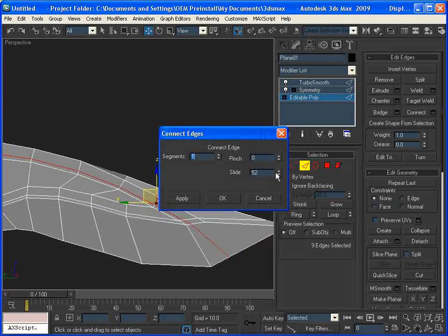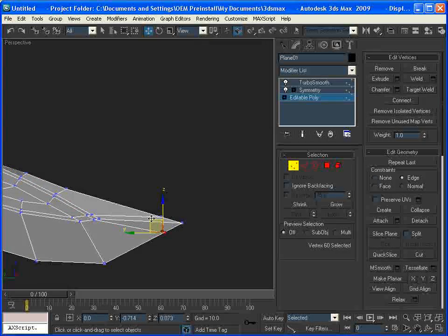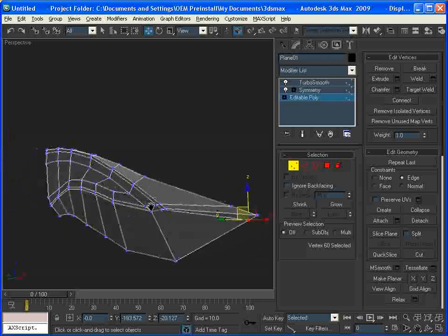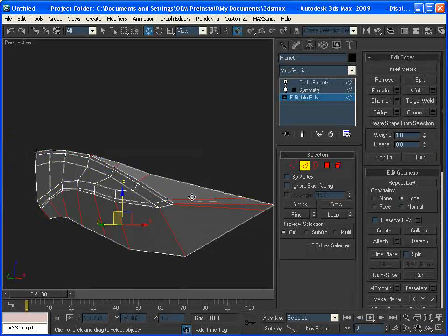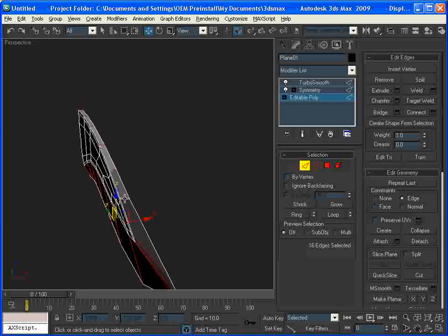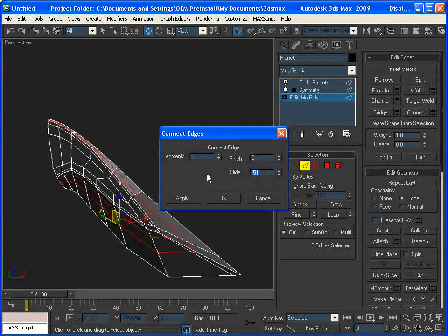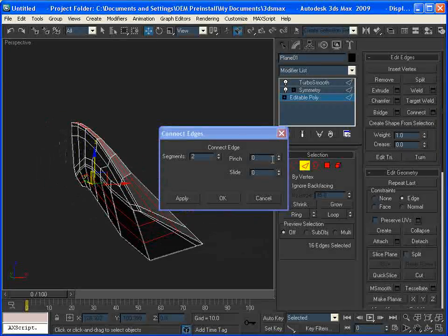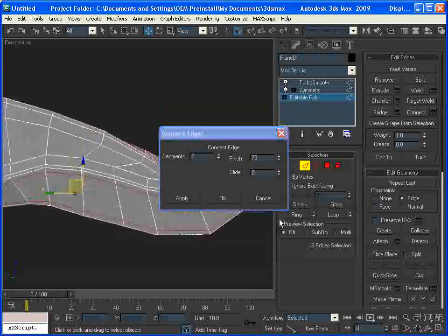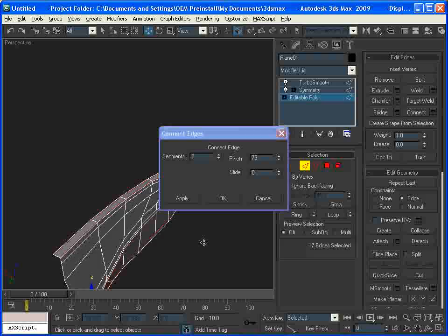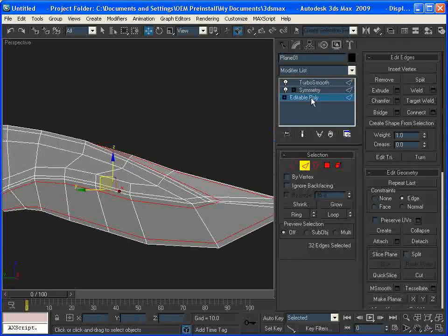And do that twice here. What this does is you'll have a higher polygon density around the hard edges that you create with this connection thing, and because of that, when you subdivide, you'll have a greater level of subdivisions in those areas with the higher density. Or not a greater level of subdivisions, but rather the subdivisions that you do have will cause those greater density areas to have more faces and therefore be sharper.